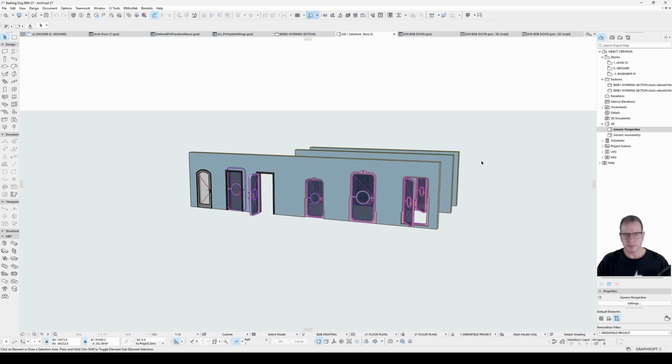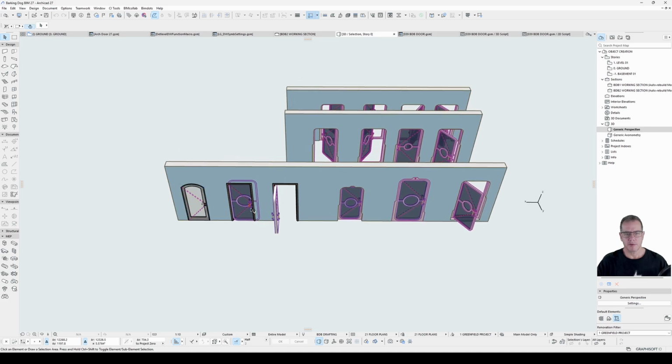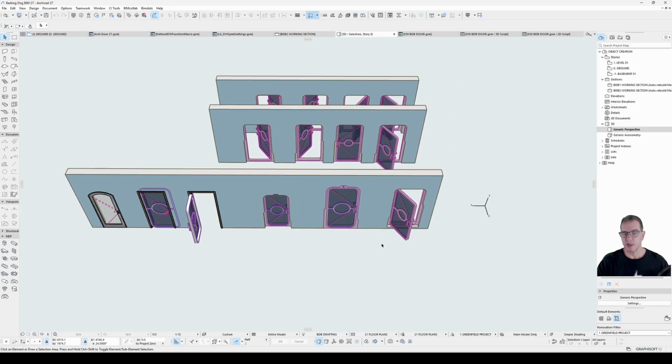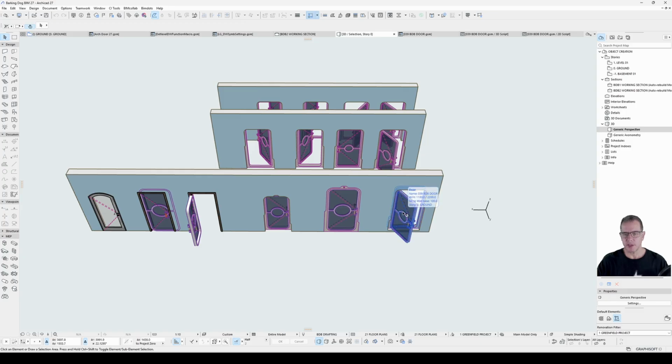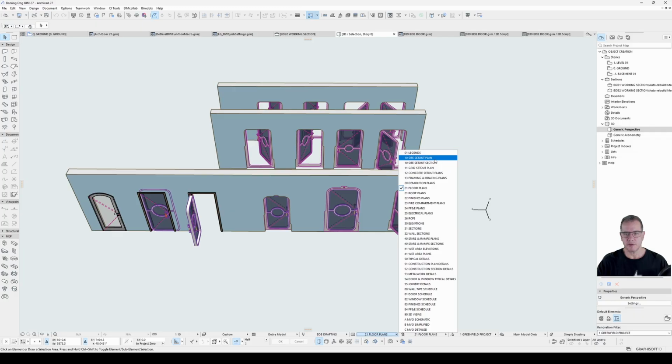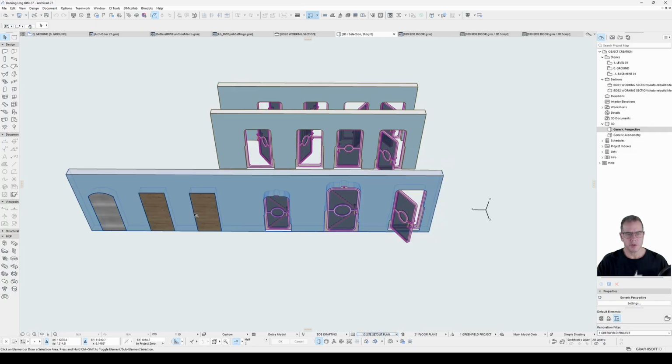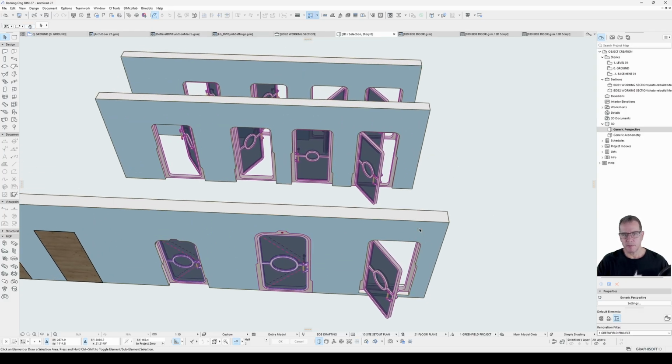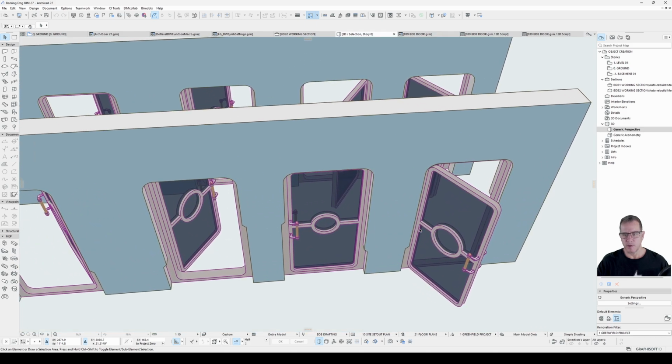Open these. These are my Graphisoft doors here, here, and here. These are the doors I've created using the two save as methods, or the two save your geometry methods, and this is my GDL door here and across the back here. If I change the MVO to a detail level that's low, these doors will update. They're the Graphisoft doors, but the rest of them don't. These two just don't respond to the MVO at all. But because the remainder are scripted, I can deal with that.